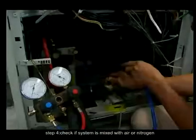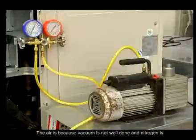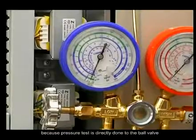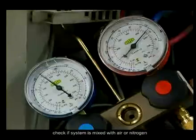Step 4. Check if the system is mixed with air or nitrogen. The air is because vacuum is not well done, and nitrogen is because the pressure test is directly done to the ball valve.